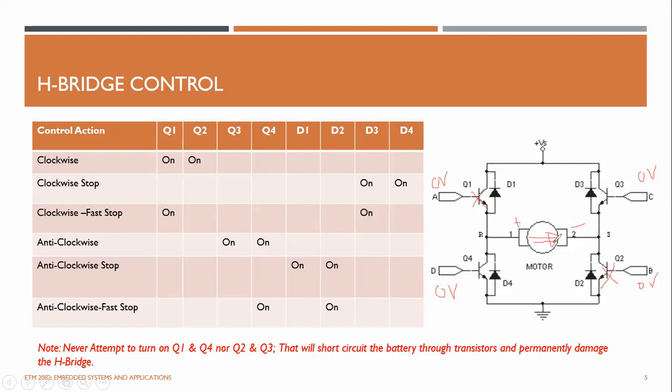Now this current is coming to here, and all the transistors are now turned off, right? Because these two were turned off from the initial state, but these two were turned on. Now they are turned off, right? This is turned off now, Q1 and Q2. So the current has no way of flowing there, and the current cannot go through this diode because it's reverse biased. So now the current can go through this diode, right? Because the current direction is here.